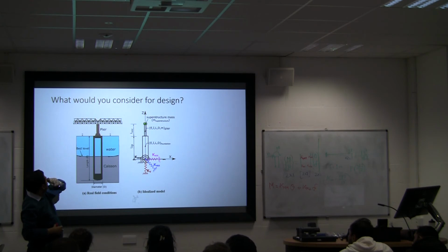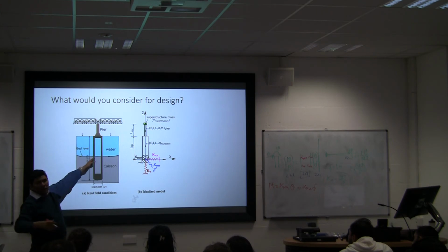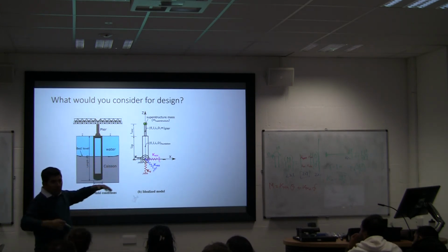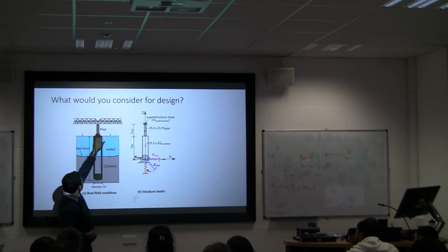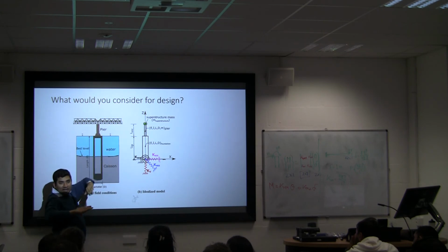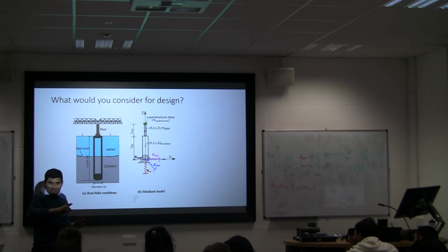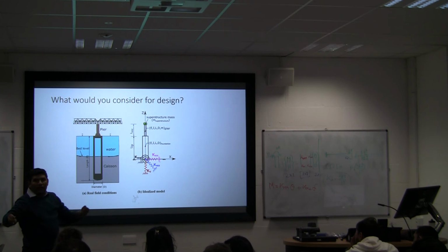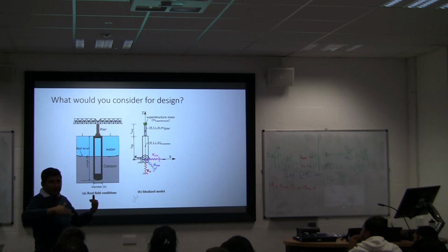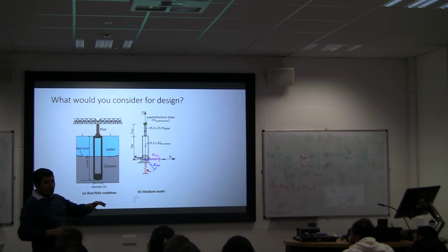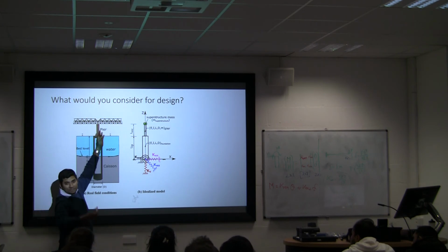Think about this condition. This one is a 123 meter span. So you have a condition where you put the deck on one side and the other side has got no deck. When you are trying to install the bridge deck, there can be a condition that there's only deck on one side while the other one is being launched.